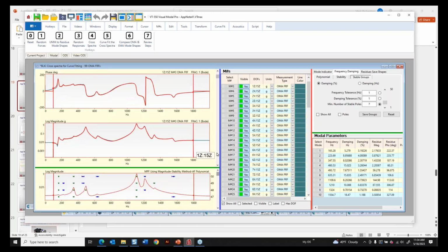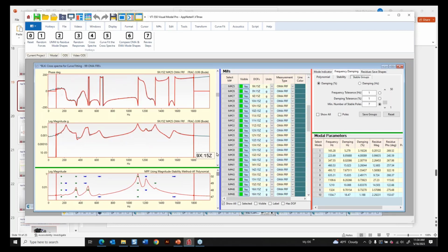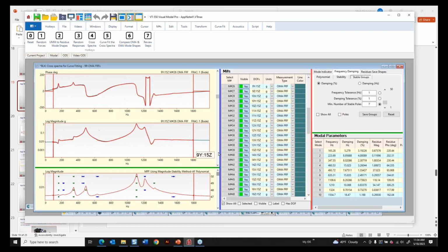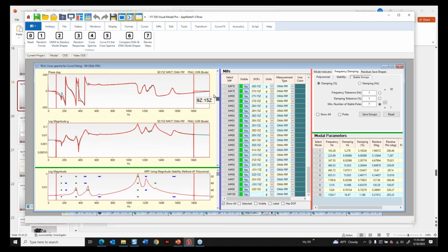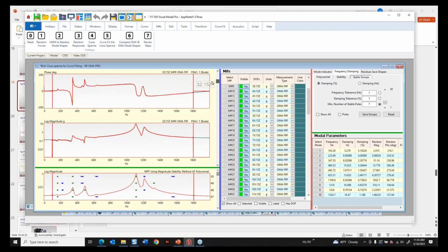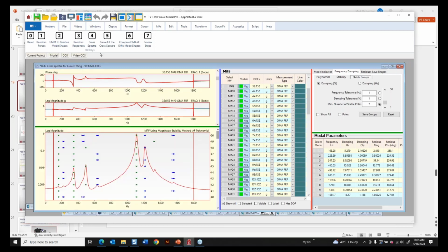So we found 10 modes, frequency and damping, and you can see as I scroll through here, the different measurements, the only thing that changes is the magnitude and phase of the residues. Those are the numerators. The frequency and damping are assumed by every curve fitter, and certainly in modal analysis, we assume the frequency and damping to be the same.